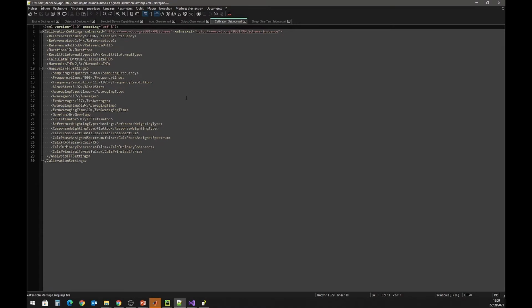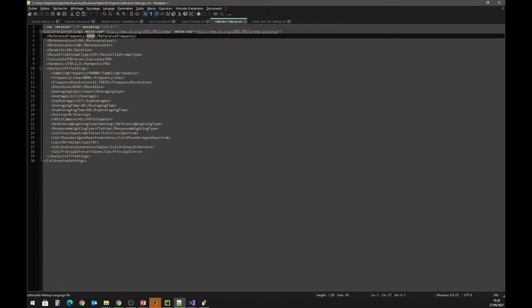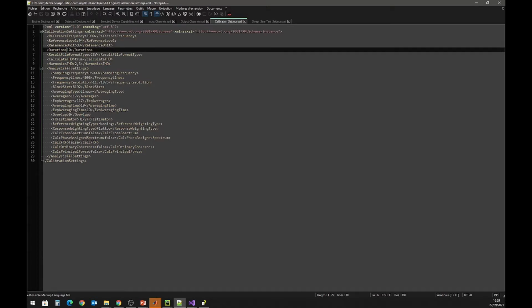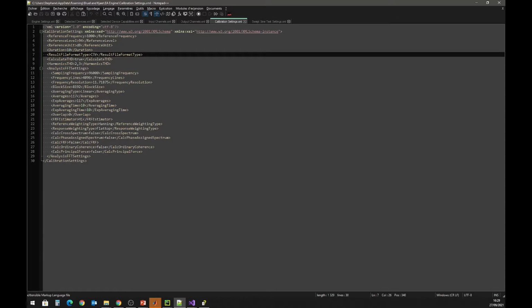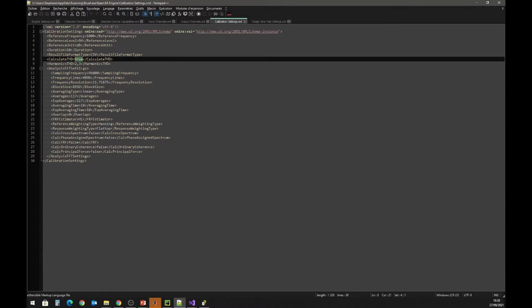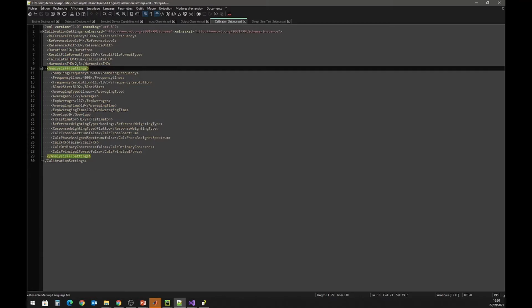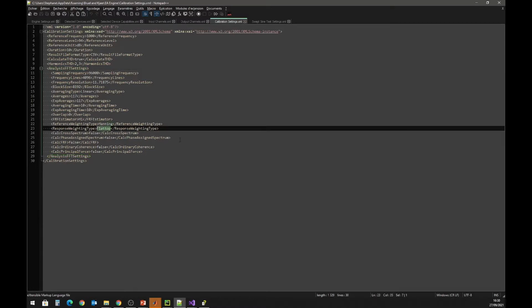If we look, for example, at the calibration settings file, this is where you will be able to define the reference frequency, reference level, reference unit, so you can run in dB or engineering unit, the duration, the file format of the output file, and here if we want to calculate THD and what harmonics to use for the THD calculation. And as for calibration we run with an FFT analyzer, you have a section dedicated to the FFT settings, like the sampling frequency, frequency lines, block size, averaging type, number of averages. Some parameters in fact are linked together and updated automatically by the engine behind the scenes. Here the reference weighting window, the response weighting window. So for example, for calibration by default it's put in flat top, etc.